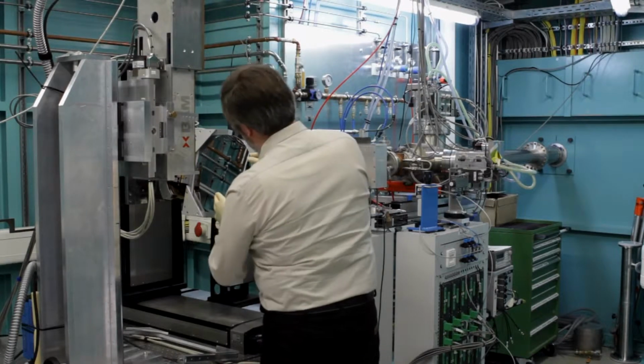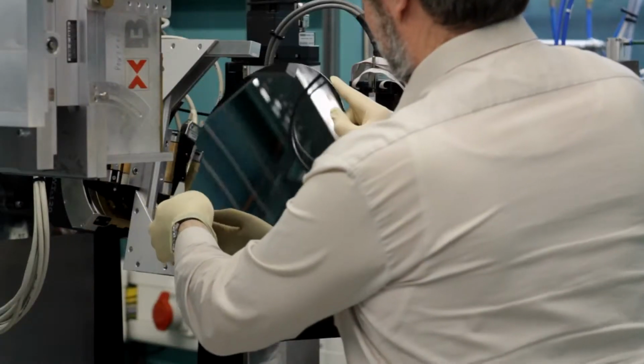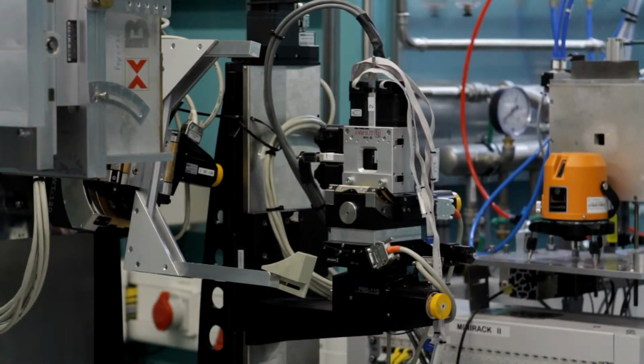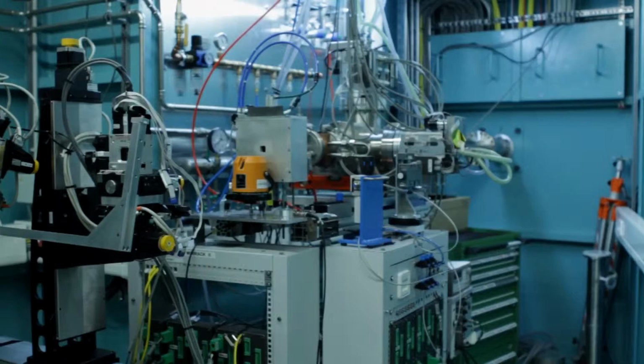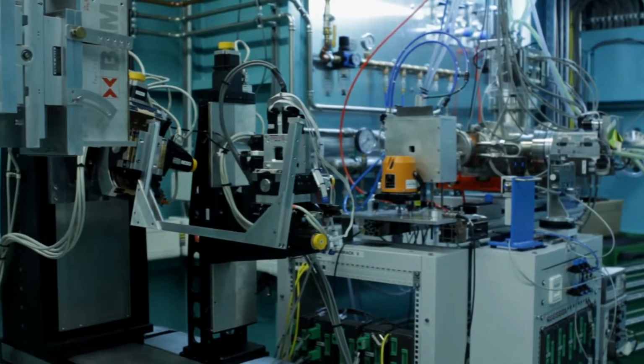This is first of all a very big goniometer where we can handle wafers up to 300 millimeter diameter, but also tiny samples. And for the smaller samples we have a heating equipment where we can go up maybe 1100, 1200 degrees Celsius for the high temperature in situ experiments. We checked again the crack formation in samples before a heating experiment. Then we inserted the heater and we looked in situ up to 1100 degrees how a crack was formed and propagated through a wafer, and a lot of thermal slip bands were also formed, and the interaction of these dislocations and slip bands was also documented in real-time movies.